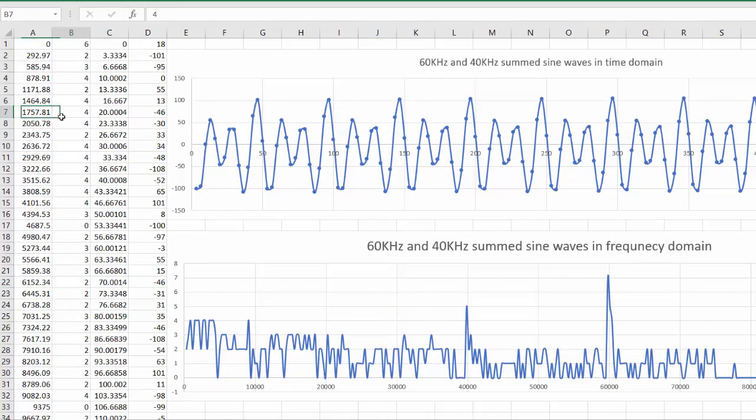And here are the frequency domain readings. This is the x-axis, which is frequency. This is the y-axis, which is, I guess we could say, amplitude. And then in the time domain, this is the x-axis, and this is the y-axis. As I mentioned before, the ADC can only do 0 to whatever the voltage reference is, and in this case, it's 3.3 volts. The function generator outputs a signal that is not negative because I added DC offset. But then in the software, I subtract the offset. I hope that's not confusing. But that's why you're seeing below 0 readings with the ADC.